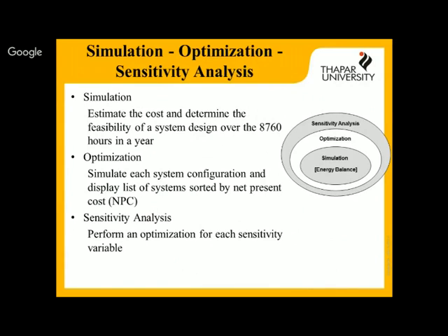Now it's up to me whether I'm looking for the more economical option or the more reliable option. It is not going to tell us that this is a reliable system. Suppose PV system plus battery plus DG is the most reliable system in this case. If I have a 20 kilowatt peak load, I can put just a generator of 20 kilowatt.